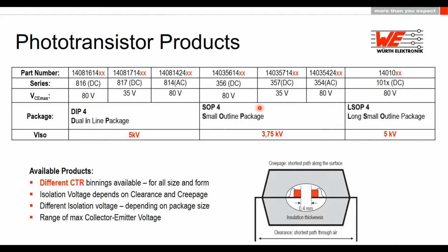These isolation voltages depend on the package size, as I told you, the creepage and clearance. These values are really important for the isolation voltage, and this package has lower creepage and clearance distances. This is why the voltage is also lower.